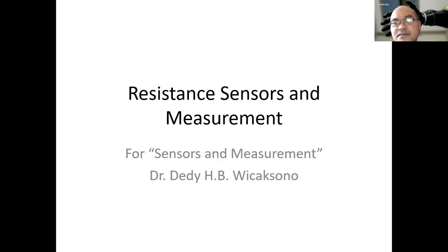The first type, which is quite common and widely used in the industry, and also in biomedical instrumentation, especially for measurement related to biomechanics, to detect biomechanical signals, is the resistance-based sensor. In a resistance-based sensor, the physical domain signal is converted into resistance change.